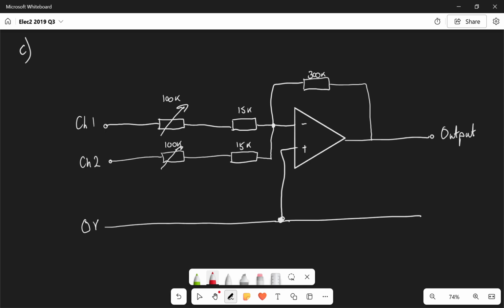All right, so the question is, here is the specification for an audio system mixer. Number of channels 2, input impedance both channels greater than 10 kilo ohms, voltage gain both channels variable from 2 times to 20 times. The following circuit is proposed as a suitable solution. I've got it here on the screen. And it says evaluate this circuit as a solution that meets the specification given above.